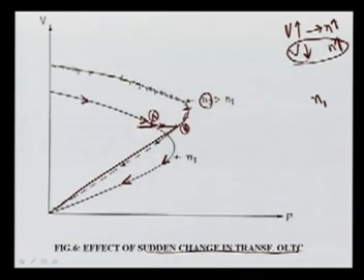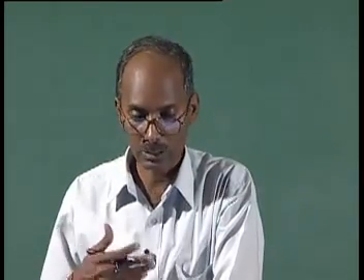zone, and once it has landed here, it keeps on reducing and finally your voltage will go to 0 and your system will collapse. So, this is also one concept. OLTC transformers sometimes, although they try to improve the voltage, also give the voltage instability case.